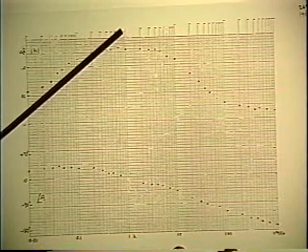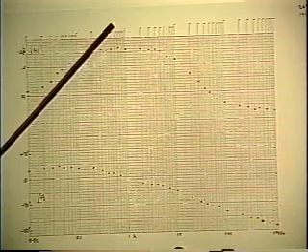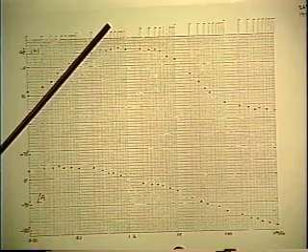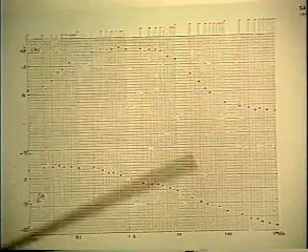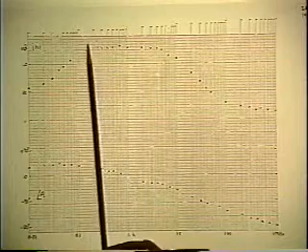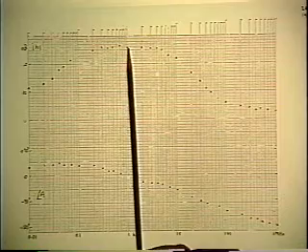But that doesn't help. You know it's got to be a multiple of plus or minus 20 dB per decade, so you have to take the right slope. Once you've done that, of course, you've identified now a corner frequency, which is an inverted pole relative to the reference gain that we started with.